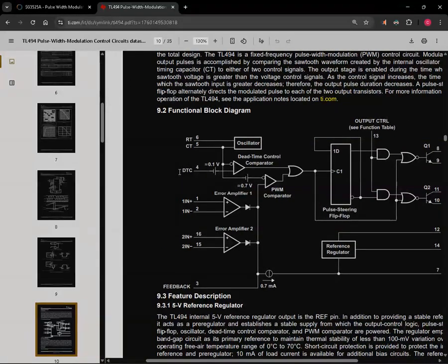To analogically have a dead time control, right? But you know that is analog, so it can have fluctuation and variation when it comes to the resistor tolerance that you're going to use. It will not be precise exactly because it's analog. Before I go to digital, the digital doesn't make the analog determination.